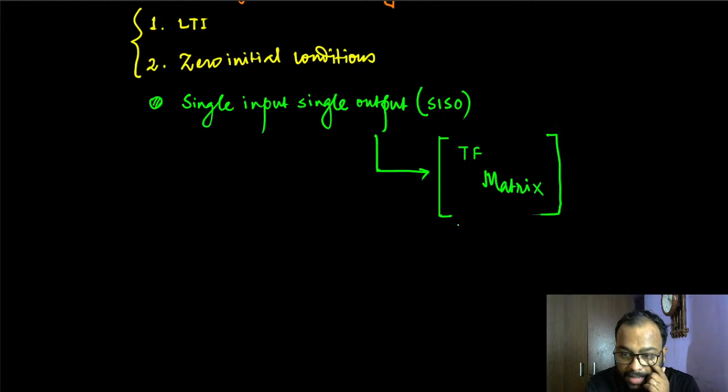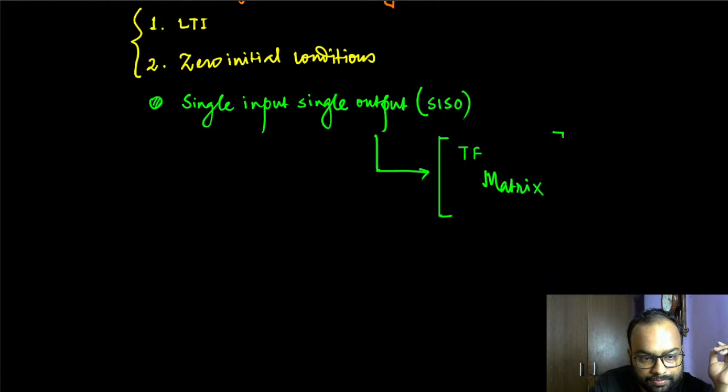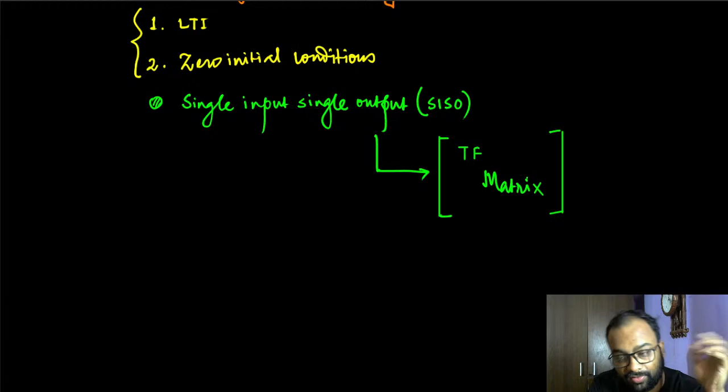This idea is really difficult, and we have pretty big transfer function matrices. For example, if we have two inputs and two outputs, then this becomes a transfer function matrix that has 4 elements in it. So essentially we are dealing with 4 different transfer functions.